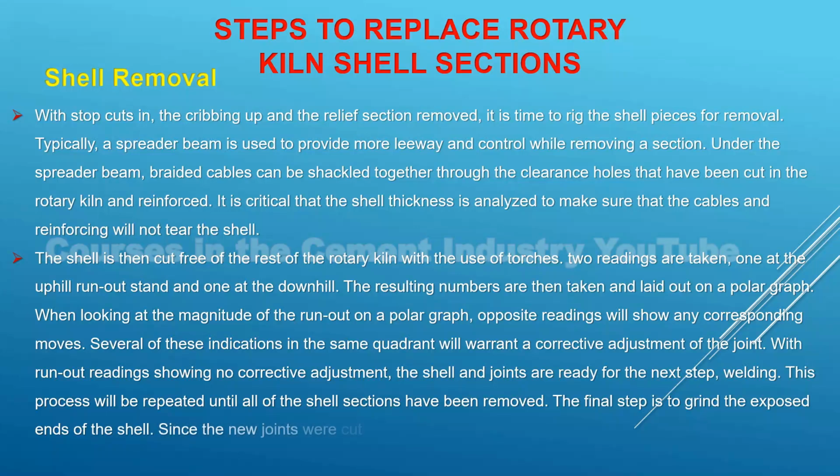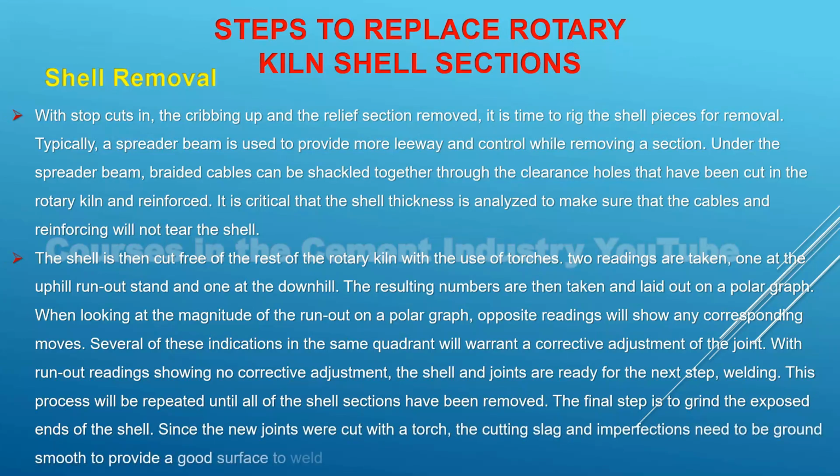The final step is to grind the exposed ends of the shell. Since the new joints were cut with a torch, the cutting slag and imperfections need to be ground smooth, to provide a good surface to weld.